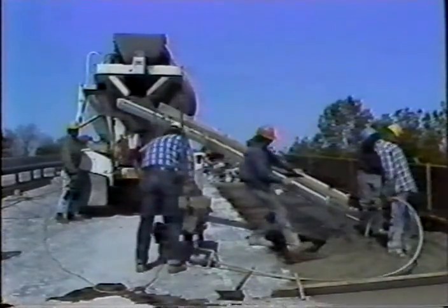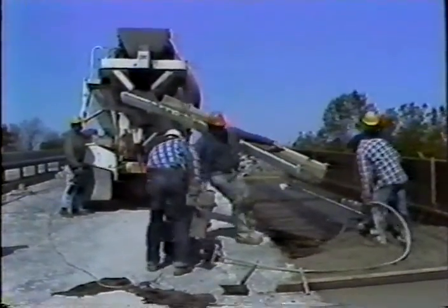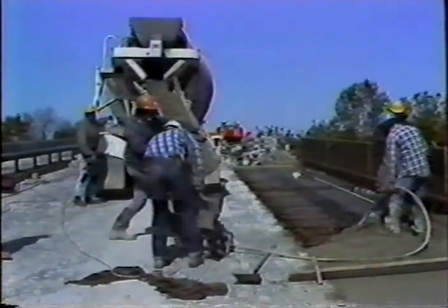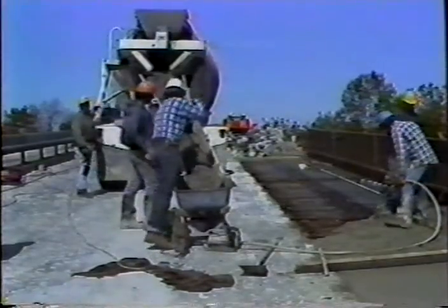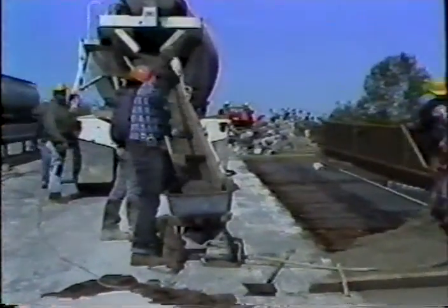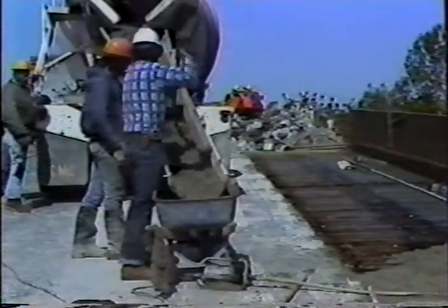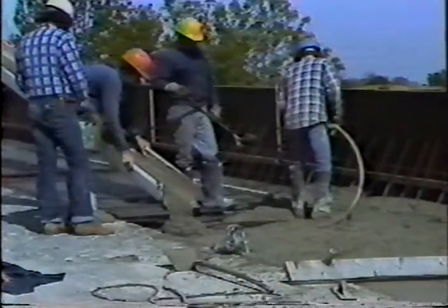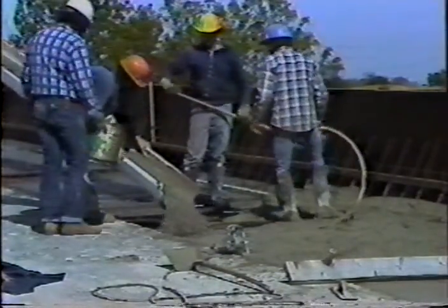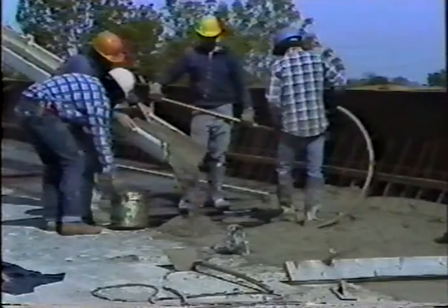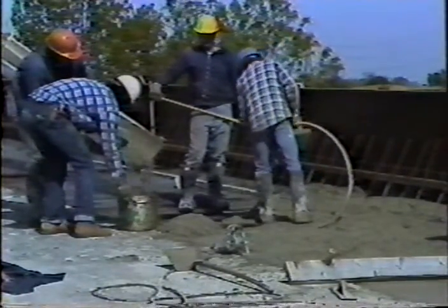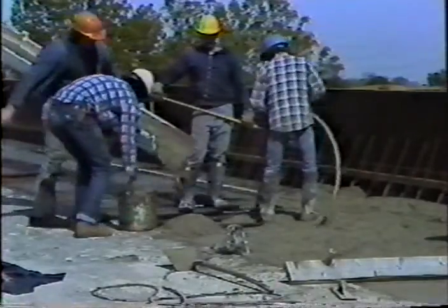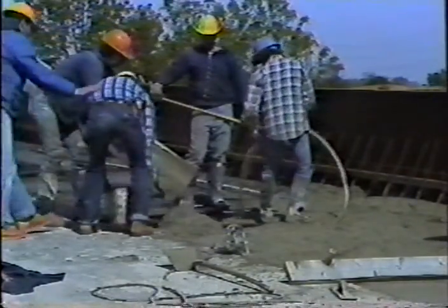Either catch the entire stream in a container or swing the chute over to the side. The important point is this: get the entire stream. Be sure to get enough concrete to run all of your tests without reusing any of it. Cutting the stream in half like this is unacceptable. The rim of the bucket will knock some of the large aggregate out of the sample. Remember, a reliable test calls for a representative sample.